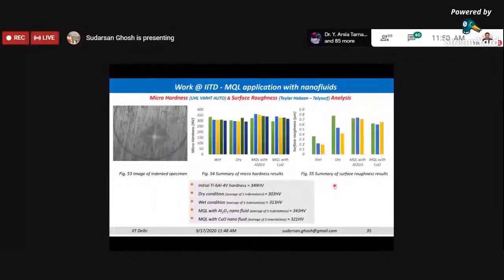Now, this higher roughness has happened mainly because the grit sizes in the wheel which we have chosen were on the higher side, and the grits have also not got fractured because of the high temperature. The grits retained their sharpness, and consequently the sharper grit has resulted in higher surface roughness.